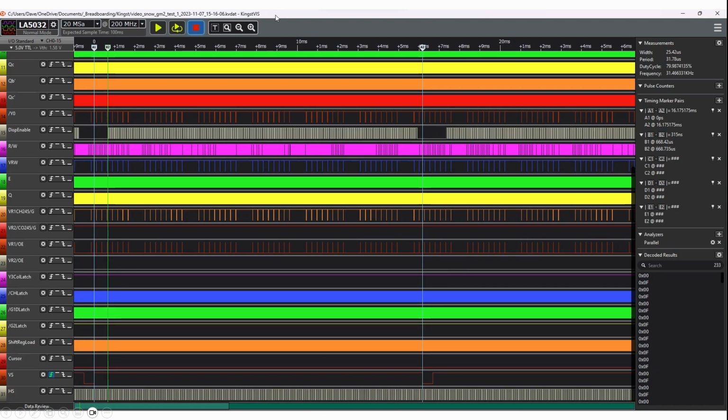Then this was looking at graphics mode 2. This was the white line appearing at the top of the screen and then reappearing all over the screen. I can see here that where we're actually writing to the video RAM, we're doing this in sort of 8-bit bursts. And down the bottom we've got one video frame, so the vertical sync is going from here to here. So this is one 15 millisecond video frame.